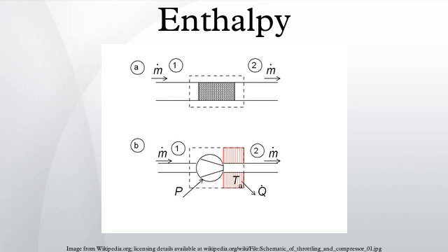Relationship to heat. In order to discuss the relation between the enthalpy increase and heat supply, we return to the first law for closed systems, dU equals δQ plus δW. We apply it to the special case that the pressure at the surface is uniform. In this case the work term can be split in two contributions, the so-called PdV work, given by PdV, and other types of work δW', such as by a shaft or by electromagnetic interaction. So we write δW equals PdV plus δW'. In this case the first law reads, dH equals δQ plus δW'.